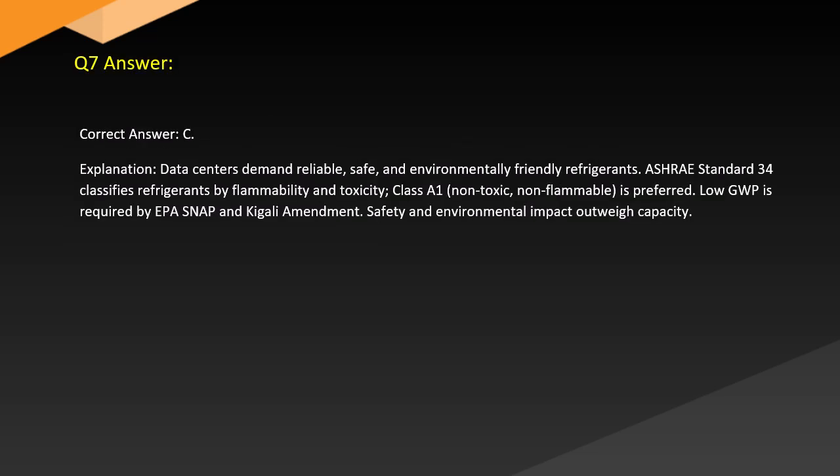Answer. Correct answer: C. Explanation. Data centers demand reliable, safe, and environmentally friendly refrigerants. ASHRAE Standard 34 classifies refrigerants by flammability and toxicity. Class A1, non-toxic and non-flammable, is preferred. Low GWP is required by the SNAP program and the Kigali Amendment. Safety and environmental impact outweigh capacity.